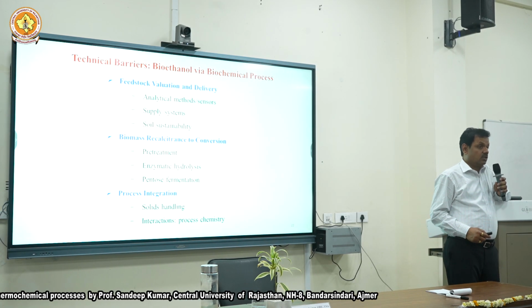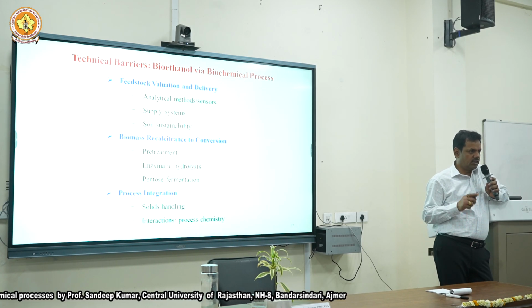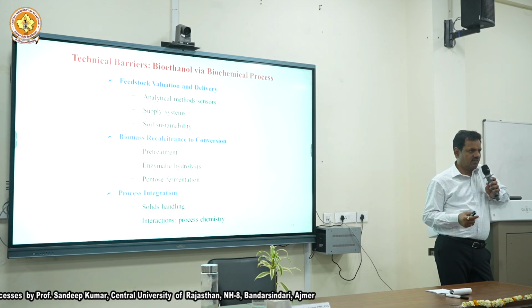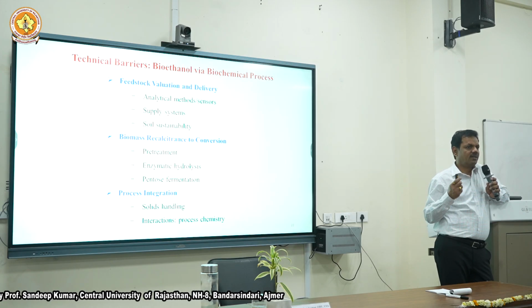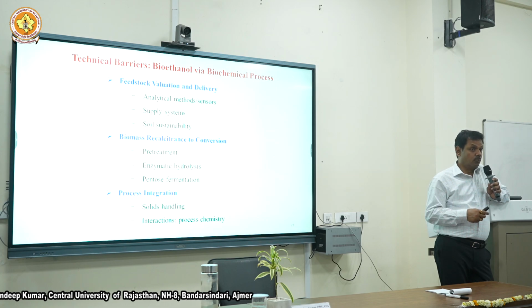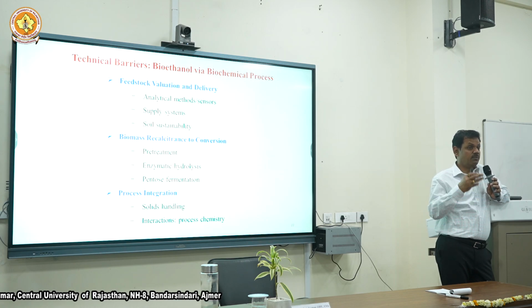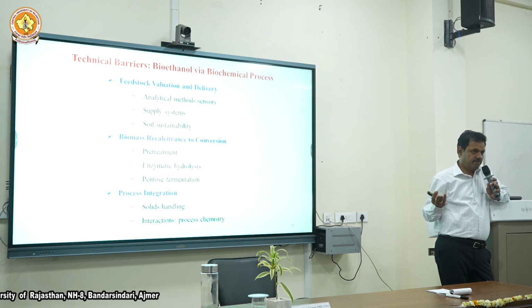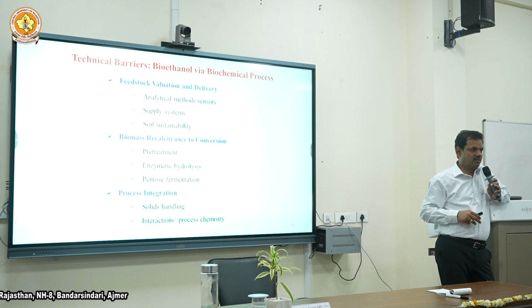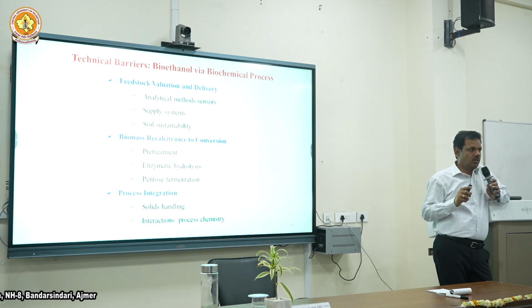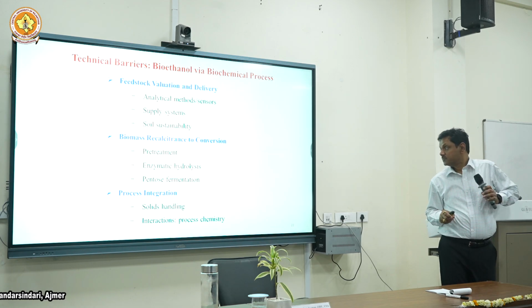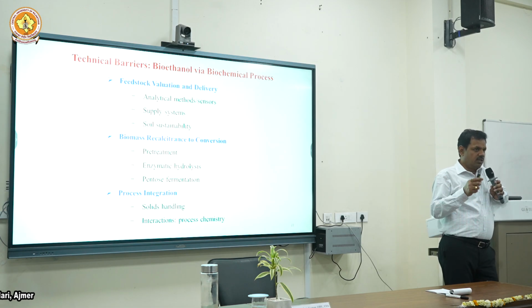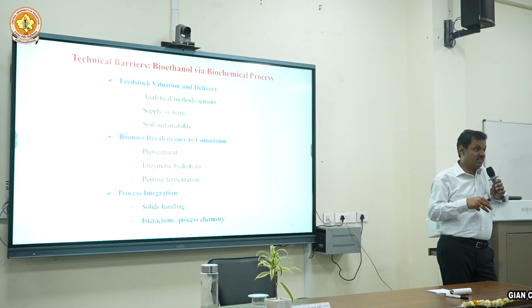So what are the different things we are handling in this plant? Solid, which is biomass, and I told you this solid is different from coal. It's fluffy, bulky, it makes bridges, it flies, right? Coal is a different solid, which is high density and flows well. So that's a challenge, solid. Solid-liquid separation. If you put water and biomass, what happens? Does it mix well? Immediately there is a wetting problem, it does not wet well, and then you have to handle that.